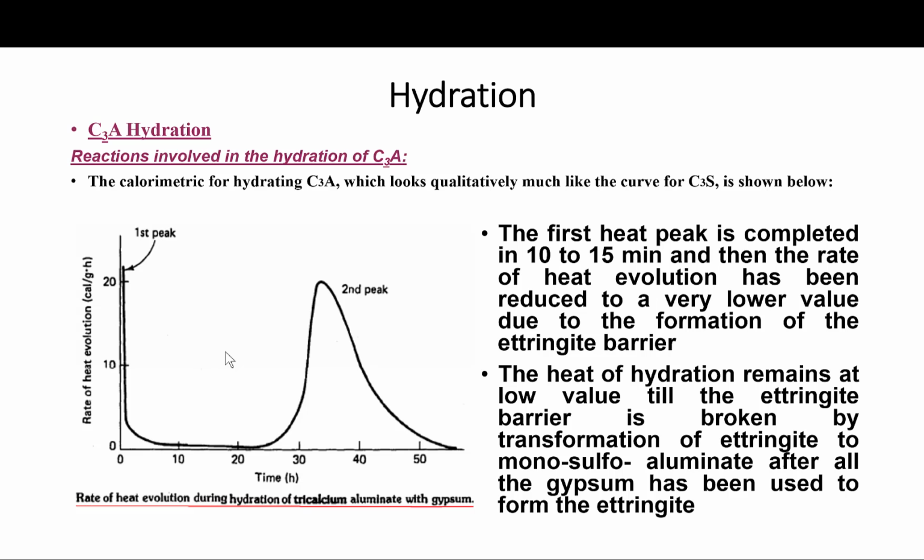The first heat peak is completed in 10 to 15 minutes. And then the rate of heat evolution is reduced to a very low value, as you can see on the curve, due to the formation of the ettringite barrier.